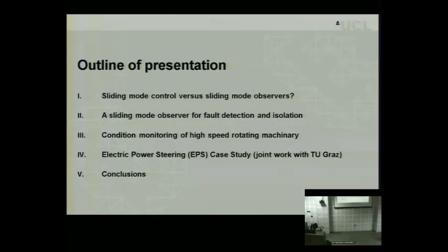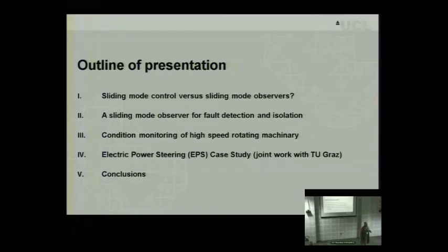And then I'm going to look at the sliding mode observer problem we had this morning, where we were talking about constructing an observer from the point of view of FDI, fault detection and isolation. And I'm going to look at how this observer gives us a very natural framework to estimate both actuator and sensor faults. So this isn't just saying there is a fault, it's explaining what the impact of the fault is.